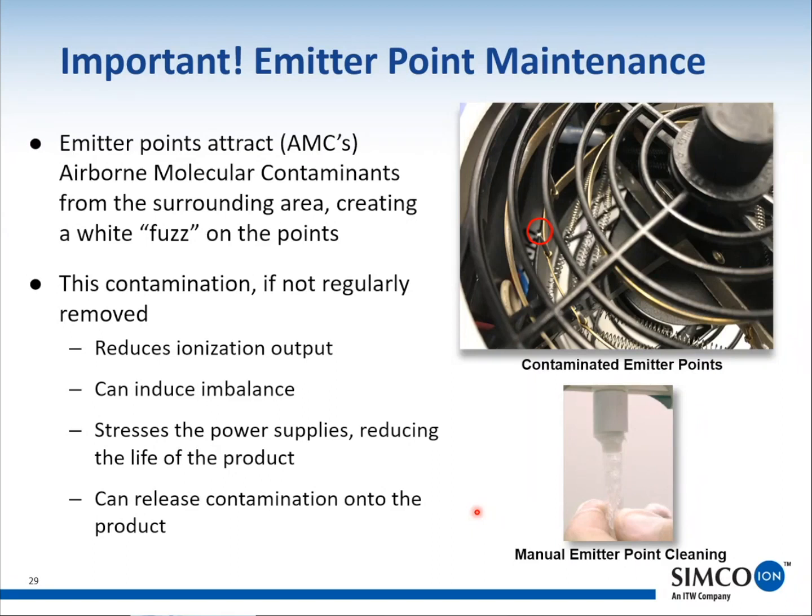But the FPD blowers, which are our highest volume blowers, and also these new technologies have 4 fan speeds. So the whisper mode, and then all the way up to, we joke that if you turn this benchtop blower face down, it would blow itself off the workbench. A lot of airflow, they're kind of noisy. Those you could probably operate 4 feet away, and you get pretty good ionization 3 to 4 feet away. So that gives you the range, probably between 1 and 4 or 5 feet, depending on the ionizer. Good question.